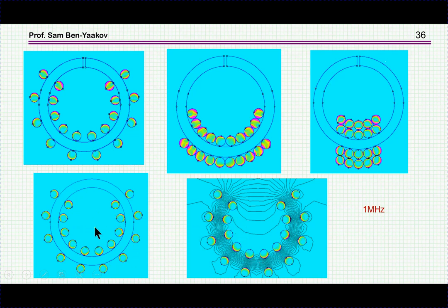In fact, it will be around 100 times lower. So therefore, to get the same inductance, you will have in the air core to add many more turns, and obviously the total loss will be much higher, although there are no core losses, but you need much more wire in order to obtain the same inductance as in these cases.